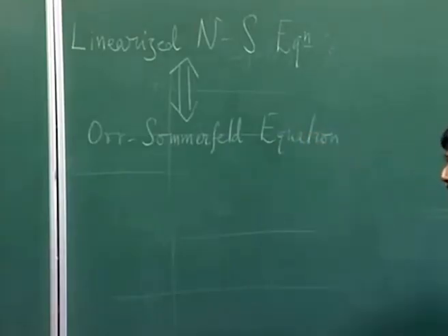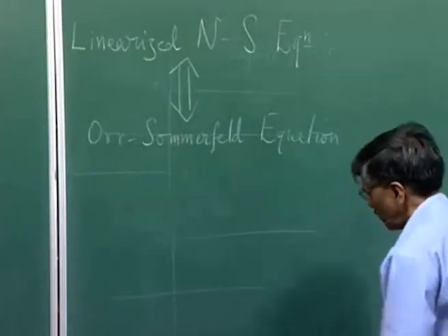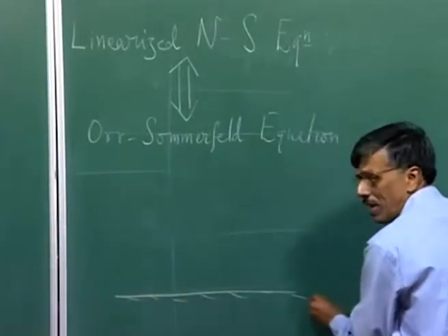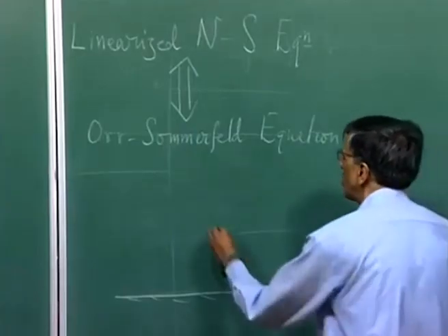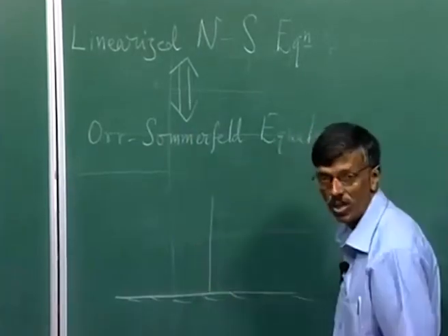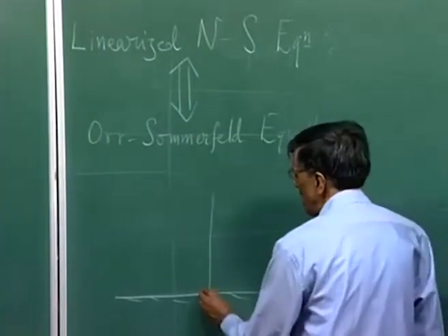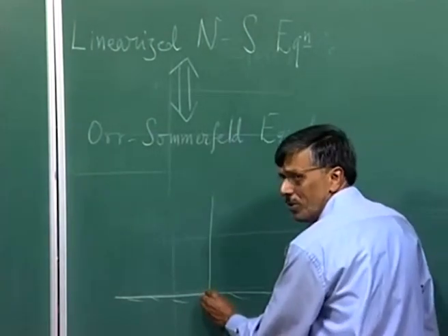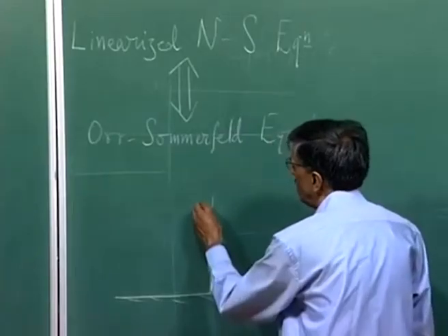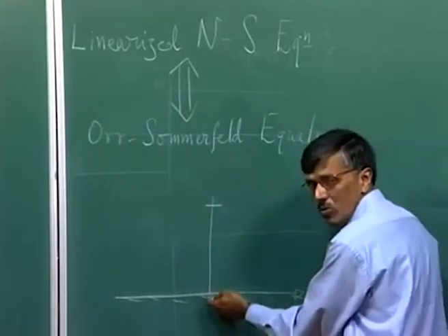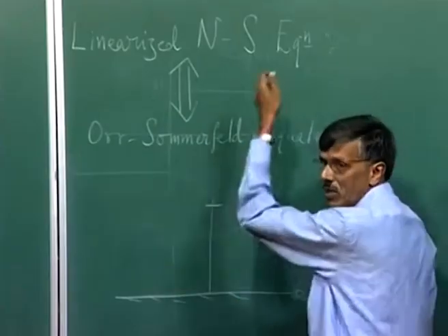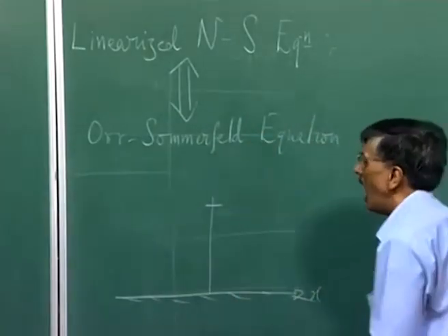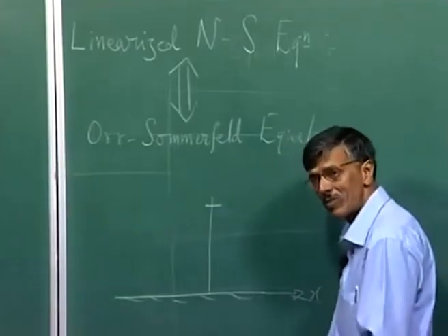Okay. And what happened? The Orr-Sommerfeld equation involves, let us say, I have this flat plate. I want to study this. Now, what do I need to study? I need to study, let us say, at a given x location. What would I be doing? I would be solving the Orr-Sommerfeld equation from y equal to 0 to, let us say, y going to infinity, a large value. And what is it that the Schubauer-Klebanoff experiment did?